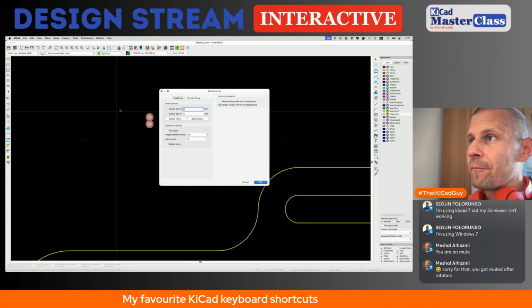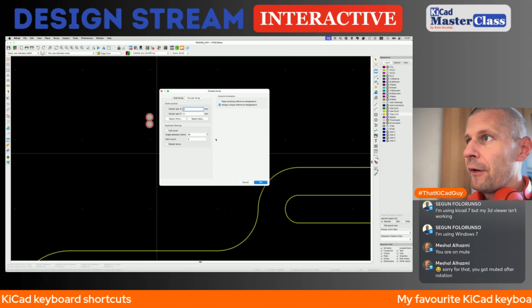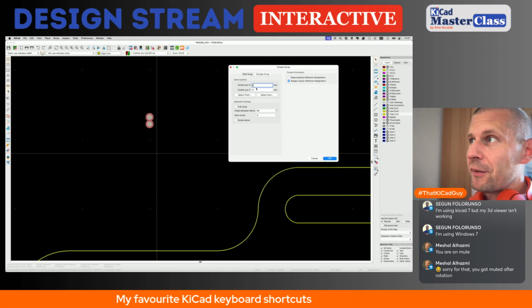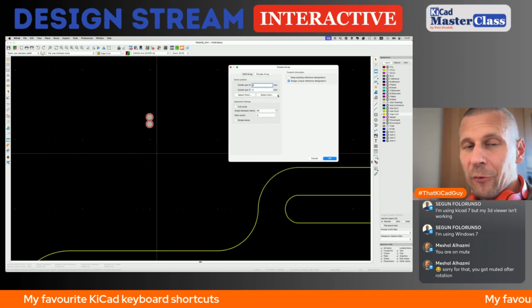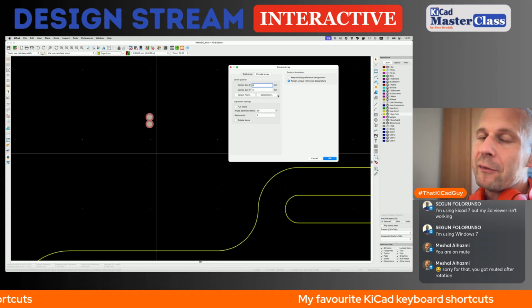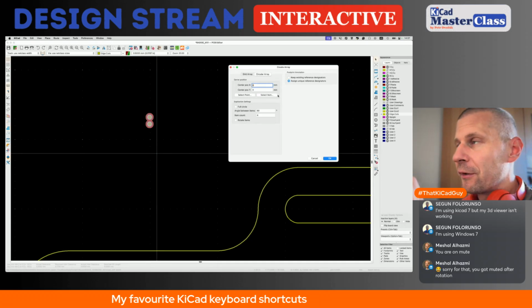You can then use it like a circular array, but in version 9 of KiCad, there are 2 new really helpful buttons. You can select item or select point. In the previous version, you had to enter manually the coordinate.